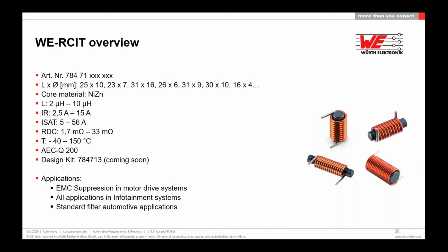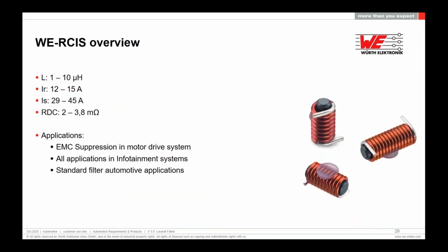But this through hole is not so easy to handle. Mostly you will need hand soldering, or wave soldering also works when you have a PCB. But if you have a PCB, I would recommend using the surface mount version. We have them with a small plateau, and that can be picked and placed automatically in tape and reel, much easier to handle.